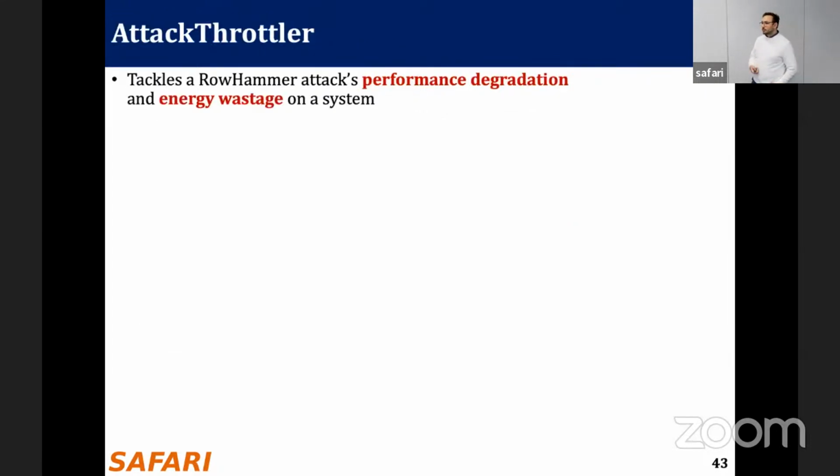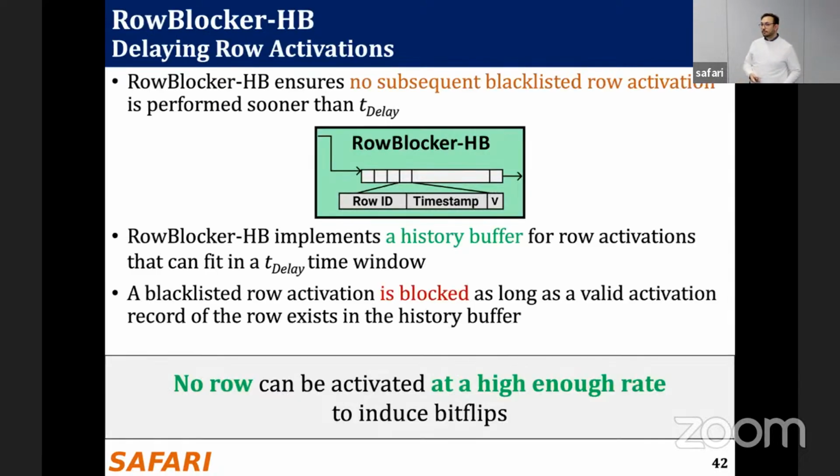The second part. I have a question. Since you have some approximate counting going on over there, you have some false positives, right? So you will blacklist some of the row accesses that are not aggressive. So it will have an effect on performance, right? Definitely. Did you consider applying different hash functions? Right now you are using counting Bloom filters, right? Yes. Did you evaluate other hash functions?